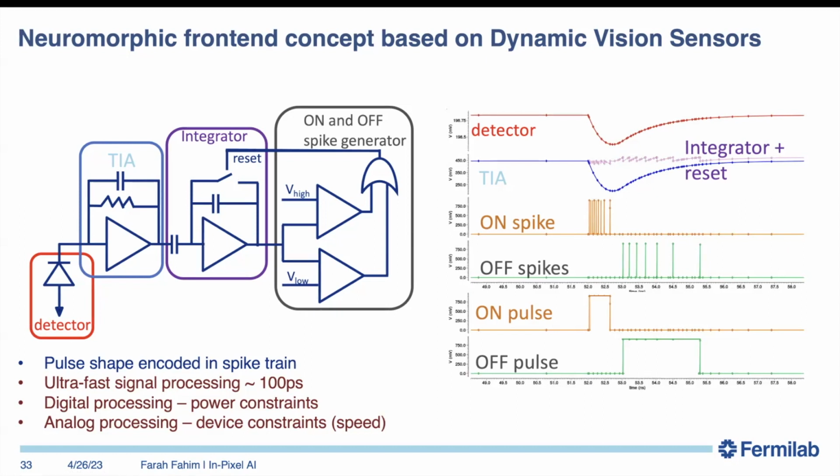But then you're not optimized for noise. And if you're trying to optimize it for speed, you can insert a pulse shaper in between the TIA and the next stage to delay things. But still not a very ideal scenario, just because of hundreds of picoseconds. If I want, I can stretch it over a few tens of nanoseconds, but probably not more than that.